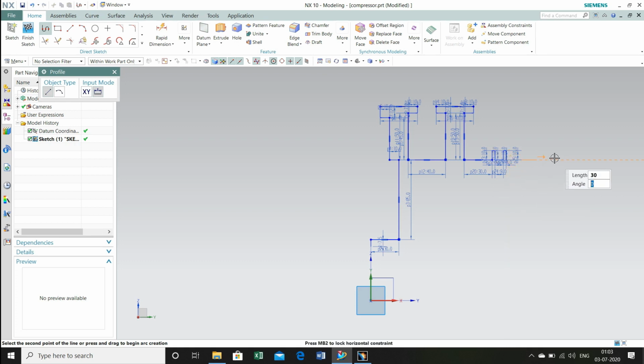Create a closed geometry to revolve this around the x-axis to create rings. That's why we have chosen an offset of 57.5 mm from starting coordinate, so that we can have clearance for the shaft in between these rings.